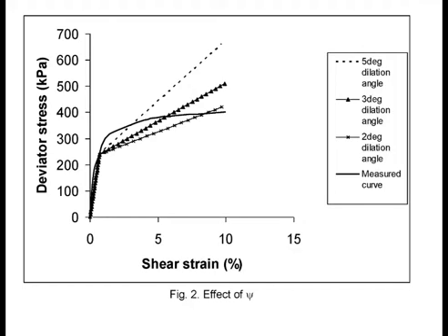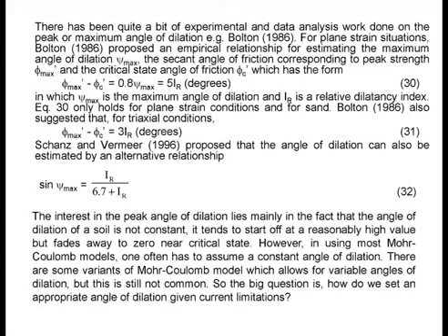Yeah, the dilatancy index, yeah. Okay, the dilatancy index is nothing more than an empirical thing that was defined by Bolton. I can't remember exactly what this dilatancy index is, but it's an empirical index defined by him. Basically, that relates the peak angle of friction to the critical state angle of friction and the dilation. It seems that a lot of people do define this. But I don't think you need to go through it. If your purpose is to get an angle of dilation, you should not need to use the dilatancy index.